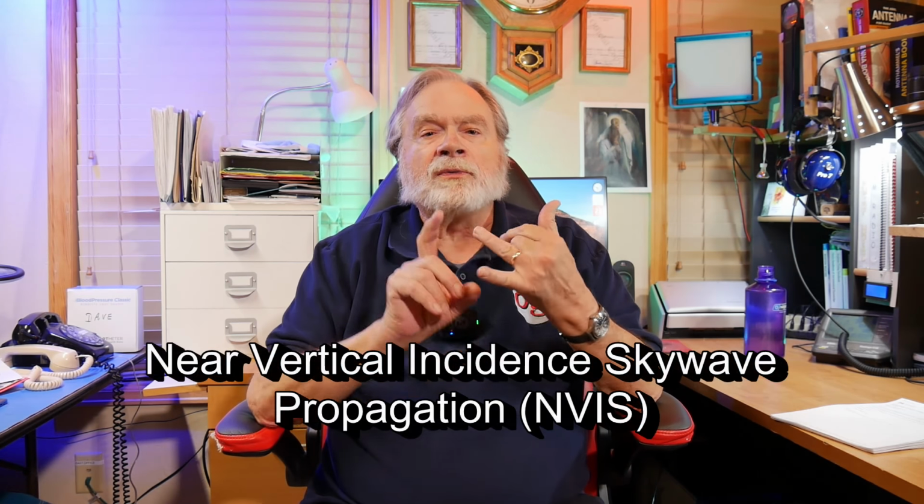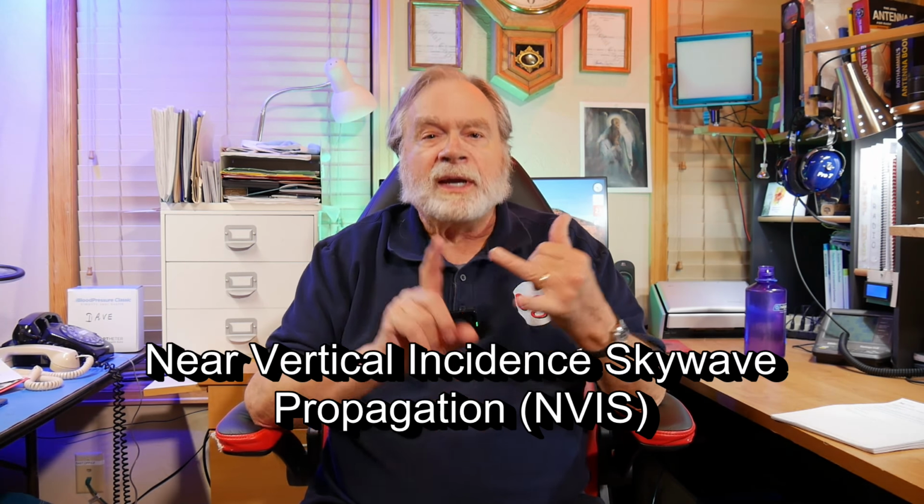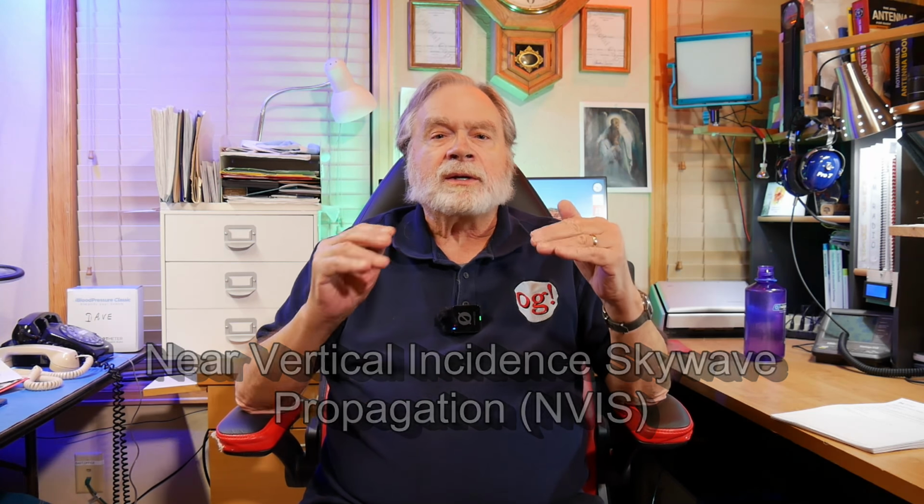There's a lot going on in this question. Let's see if we can unpack it. First of all, near vertical incident skywave propagation means propagation, usually on 80 or 40 meters, sometimes 60, that goes up, bounces off the ionosphere, and comes back down. Now that would be vertical incidence. This says near vertical, actually up to about 45 degrees or so. This transits the D layer and goes up to the F layer and comes back down.